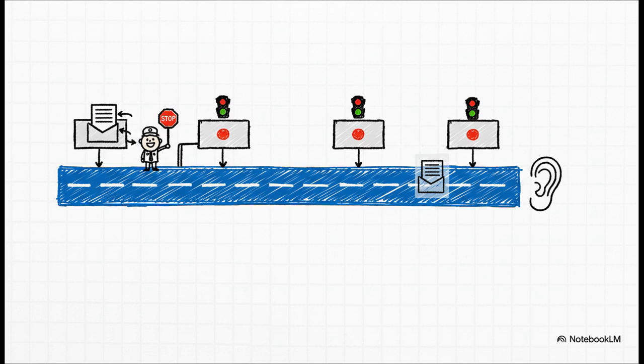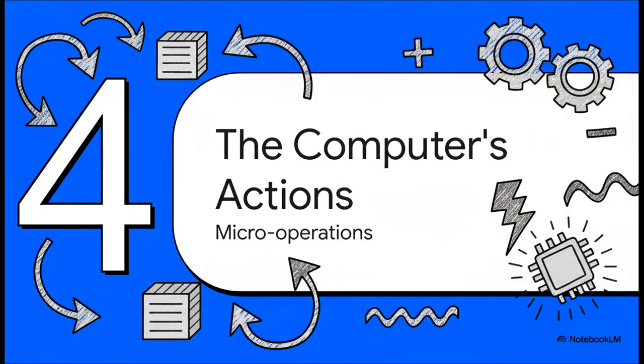It's all about discipline. Think of it like a one-lane road. Only one register is allowed to send data onto the bus at any single moment. These control signals we talked about act like traffic cops, telling one register, okay, it's your turn to talk. Meanwhile, any of the other registers can be listening and just copy that data off the bus as it goes by.